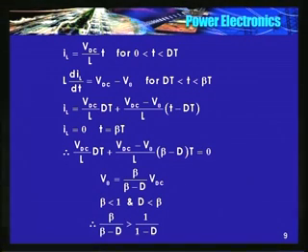When the current becomes 0, there is no current flowing now. There is no current flowing to the inductor at all. So when the current is flowing, voltage across the inductor when the switch is open is VDC minus V naught. Okay. So the maximum value of current, or current has attained its peak when t is equal to dt. This is I max. It started from 0, initial value is 0. It started from 0 because current is discontinuous.